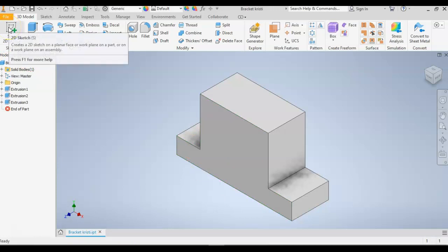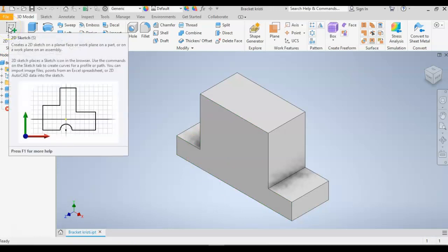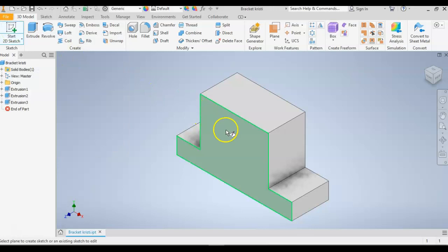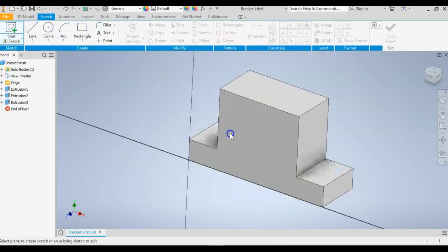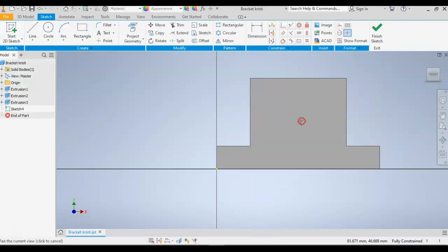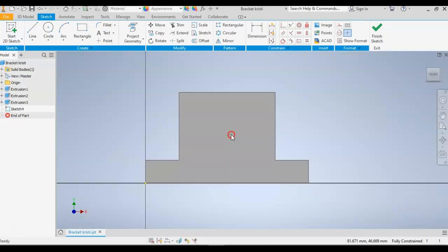So we're going to keep that repetitive process. We're going to click on Start a 2D Sketch and we're going to say, hey, I want to sketch right here. And now I'm going to use my pan feature, holding on that scroll on my mouse, and slide it around. Now I want to add a rectangle on the front. So I'm going to click on my rectangle tool. I am going to just make a random size rectangle. I want it to line up with that edge, so it's highlighted purple. Great. I'm going to click to start, and click to make a rectangle.